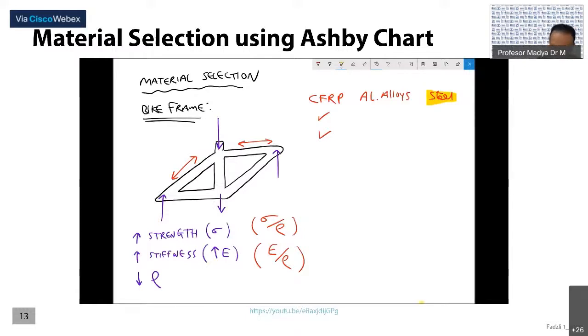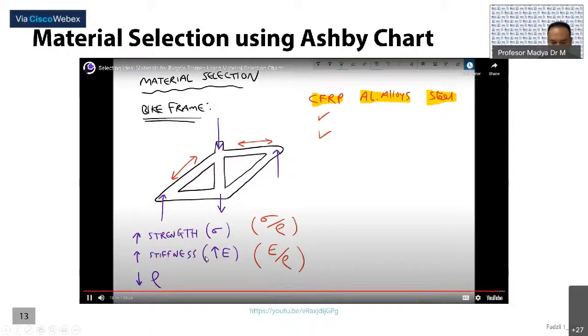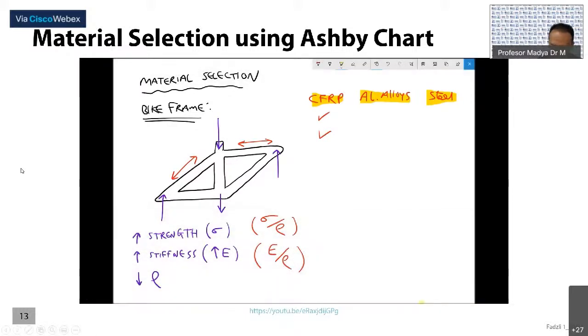So the materials are cheaper and they're easier to manufacture. When we consider aluminium alloys, the reason why aluminium alloys are used is because they have low density. They tend to be relatively strong, but also very light. But by far the strongest, stiffest and lightest materials are the carbon fibre reinforced polymers. The cost of those is greater because the manufacturing process is much more complex. And we'll look at various different manufacturing processes in a later tutorial.